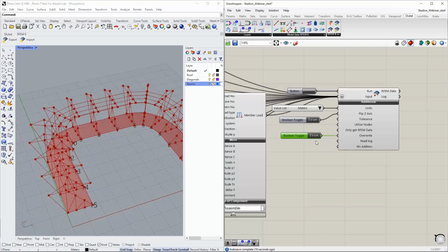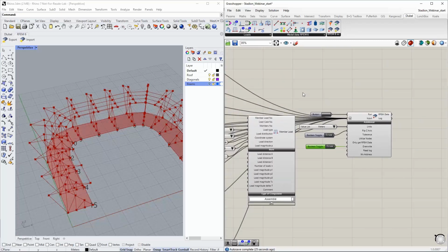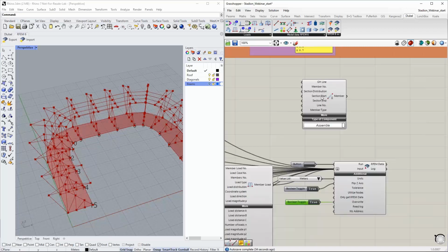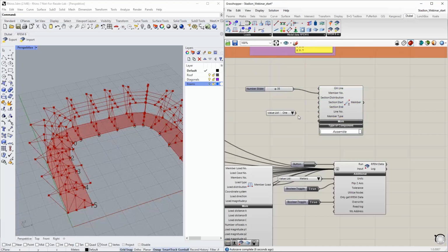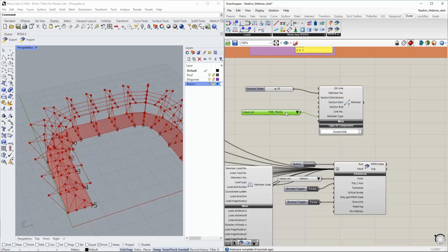And basically, we also have a modify option, because if you assign an ID to every component, let's say in RFEM 6 you already have a structure with 100 members, and you create a member here. You say, okay, I want to modify member number 35. You define member number 35 should be modified, and maybe you need to modify the member type, for example. It should not be beam, but truss member, and you put this into the export, then only the member with the ID 35 will be modified. The other components won't be touched. So it's also some kind of a modify option.